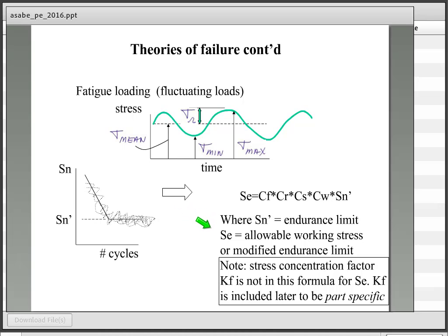By the time you consider that for fatigue application and apply a number of these factors to the endurance limit, which you can go into a handbook and find, and you can go into a Machine Design Handbook and find typical values of factors like these, you might be down to needing to design to a stress range or stress level of maybe 9 or 10,000 psi, a lot lower than what yield would be if you were dealing with static. So anyway, that's simply an area to have a little bit of understanding of.